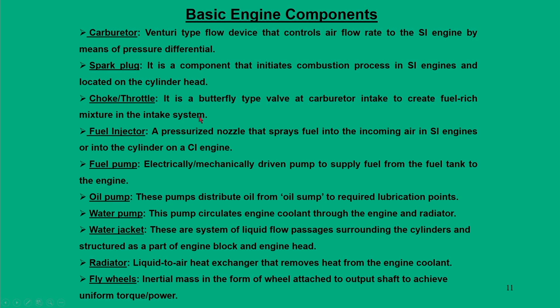It allows more fuel to enter into the engines from the fuel tank. And in particular, there are other devices like the fuel injector. These are pressurized nozzles that spray fuel into the incoming air for SI engines and into the cylinder in CI engines.